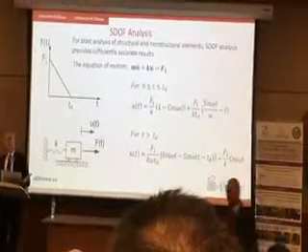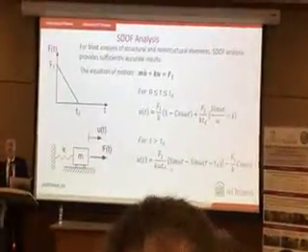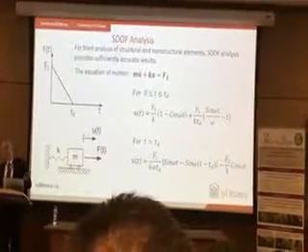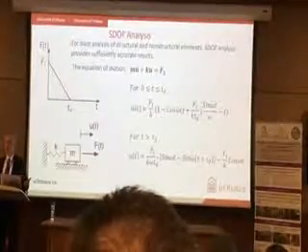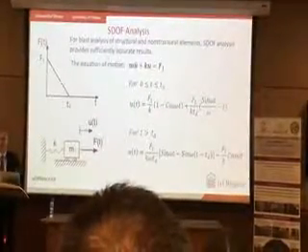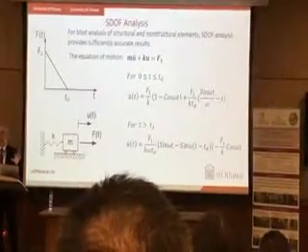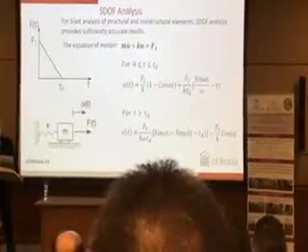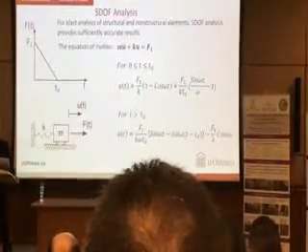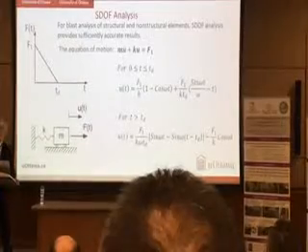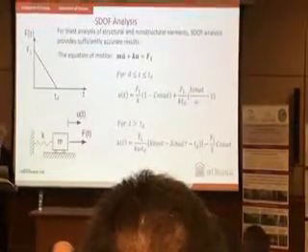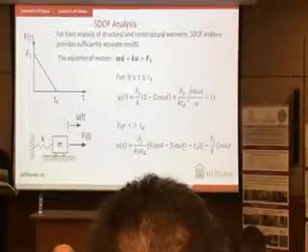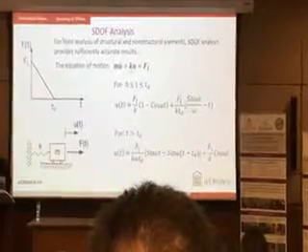So what do we do in earthquake engineering? Obviously we do multiple degree of freedom analysis. If you have a 5-story building, you have 5 degrees of freedom. Although we simplified it and use a single degree of freedom equivalent static load approach. But in blast engineering, life is even simpler because usually single degree of freedom analysis gives you fairly accurate results because these columns bend in one mode, right? They bend in a half sine wave deflected shape, and so all you have to do is do single degree of freedom analysis.